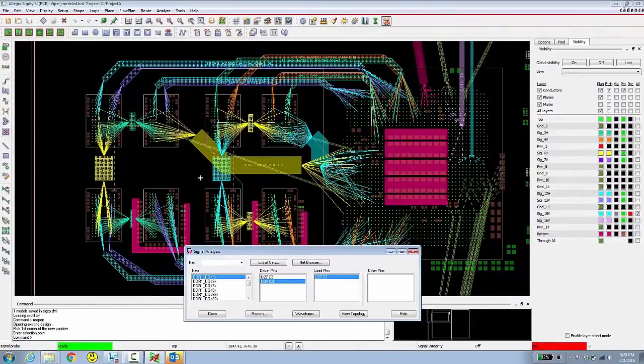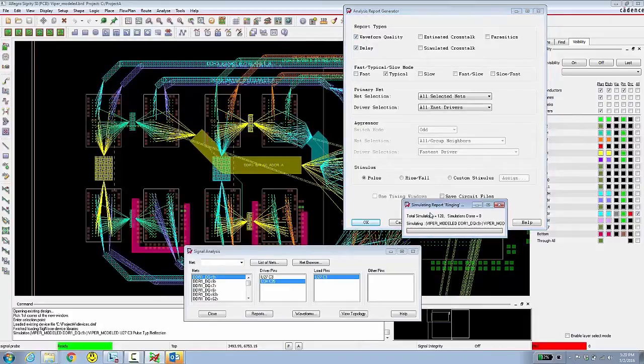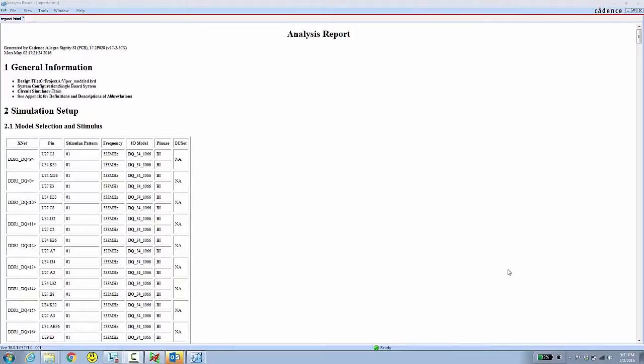If we wanted to take into account the difference in length for various nets without flow planning, it would be a tedious process to go alter the % Manhattan setting over and over for various groups of signals. This is no longer necessary now that flow planning is taken into account. If we run a simulation for the DQ nets in this interface, we can easily run all the nets in both directions and in very little time. This can generate reports and or waveforms.